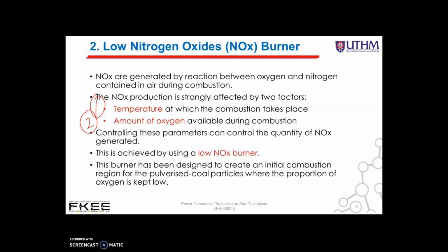Okay, so this can be achieved by using the low nitrogen oxide burner. This burner has been designed to create an initial combustion region for the pulverized coal particles where the proportion of oxygen is kept low.